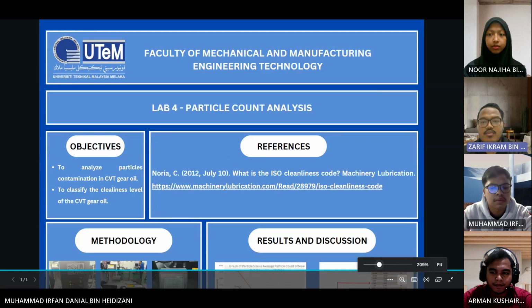Each size category should be counted, with the absolute count converted to an ISO code using the ISO range code chart. The ISO code is a fantastic tool to use for setting target alarms and establishing a goal to achieve and maintain as it relates to system cleanliness. It is also the perfect value to use for key performance indicator (KPI) tracking, charting, and posting. However, the ISO code should play only a secondary role when it comes to evaluating used oil sample data.